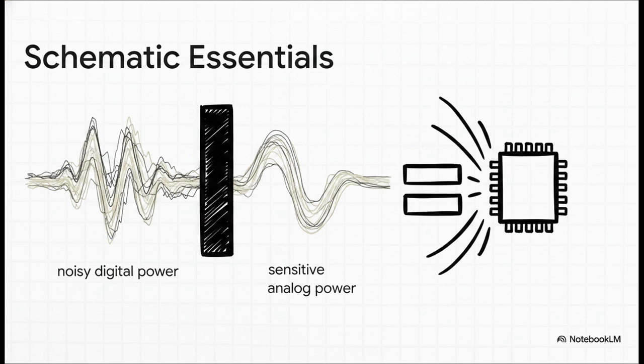Honestly, forgetting a simple decoupling capacitor right here is exactly why your microcontroller might just randomly reset out in the field the second it tries to switch a high-speed load.